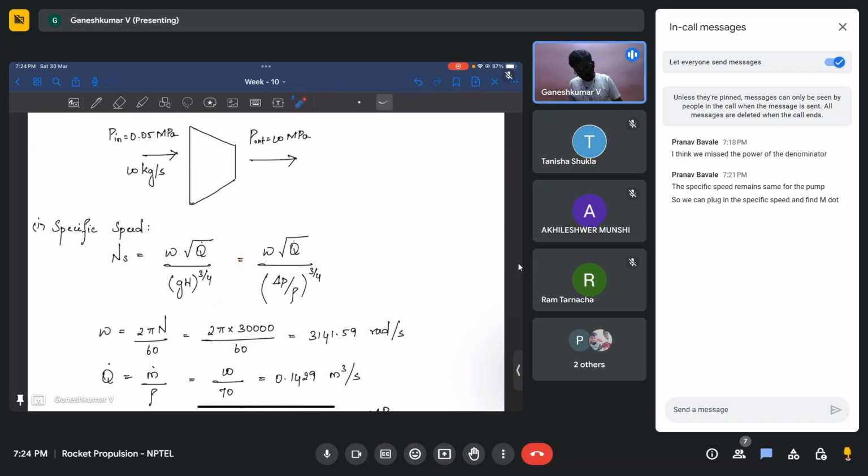And also, if you look at this equation here, let's say you increase the head. Then it's like you are trying to pump the fluid from a low head to a higher head; initially it was at h1, now you have increased it to h2. Then what happens with the same pump? Either your volume flow rate has to reduce. That is how it has to operate. So basically it links three parameters together, which simplifies the operation. That is where this specific speed is being used.